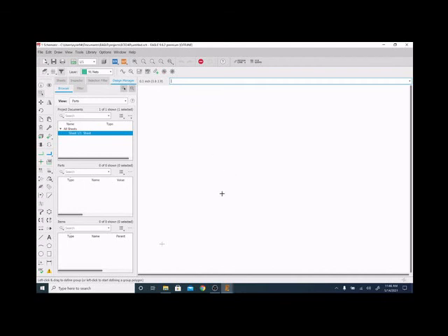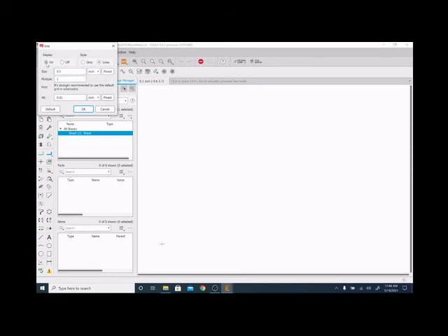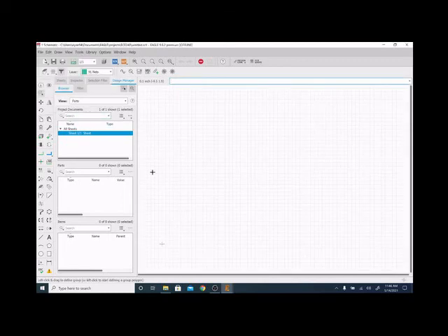This screen is where we lay out the sort of human side of the circuit. So this is purely for visual and information transfer purposes. So we want to make this as easy to understand as possible and easy for us to use as possible. So we're going to start by turning on our grid, and we're just going to go with the basic units at 0.1 inches, and we want to turn the display on. So we're going to hit OK, and we have this nice grid now.